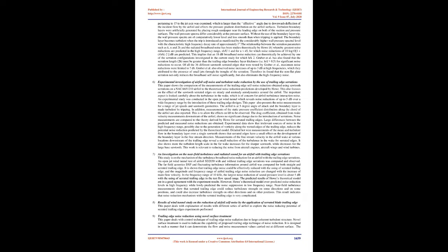Without the use of the boundary layer trip, the wall pressure spectra are of comparatively lower level and less smooth than when tripping is applied. The boundary layer becomes turbulent when the trip is introduced, as manifested by the considerably higher wall pressure spectral level with the characteristic high-frequency decay rate of approximately f^-5.